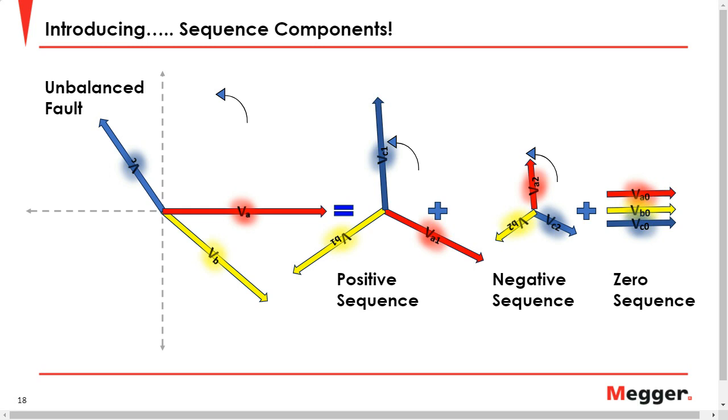However, what I have seen is somewhere around 5% of negative sequence to positive sequence. You want to keep your negative and zero sequence elements very, very tight, which doesn't mean that I'm saying that the zero sequence should be kept at 5%. That's different because zero sequence is related to neutral protection, and so there are different considerations there. Neutral and ground protection.